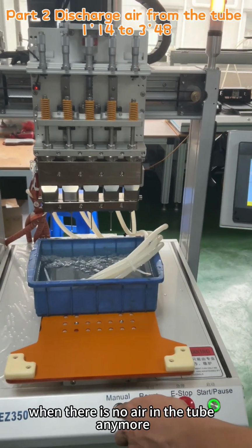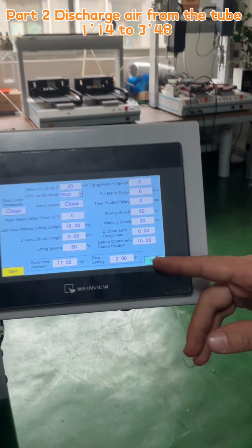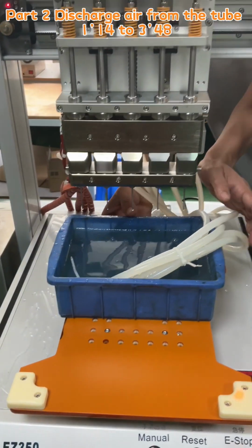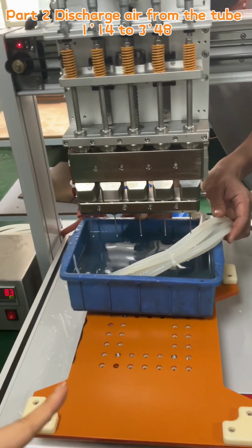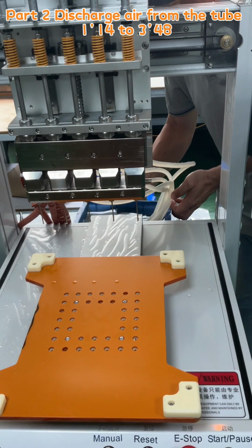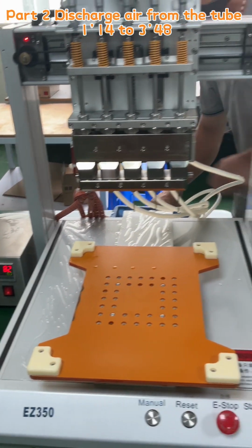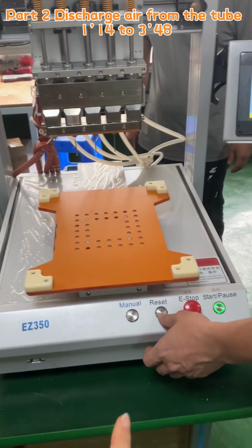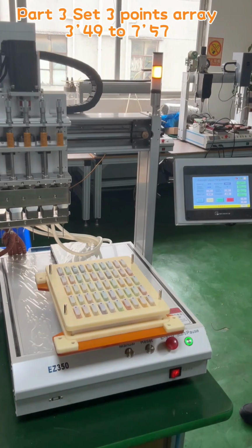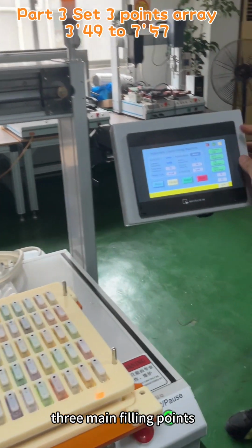When there is no air in the tube anymore, we go back to the last page and we put back the oil storage box. Then we press the reset button to make sure the filling needles are back at their original location. Next, we need to set the parameters of 3 main filling points.